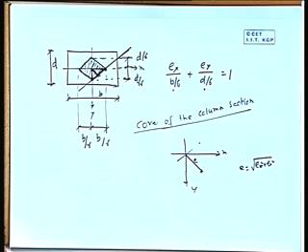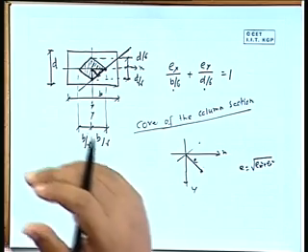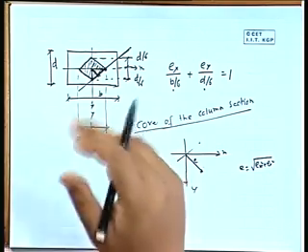The reason is the bending equation whatever we use, or we use My by I for finding out the bending stress when the member is subjected to moment. Now there is one requirement there. The bending will be acting about a plane which should have axis of symmetry.